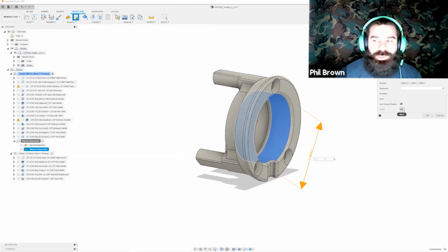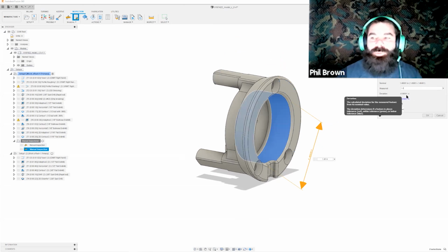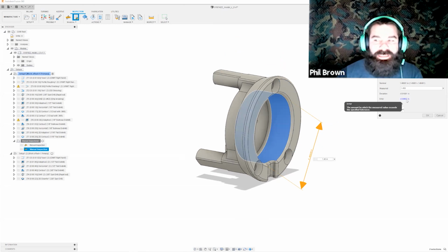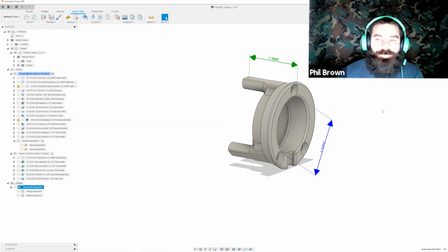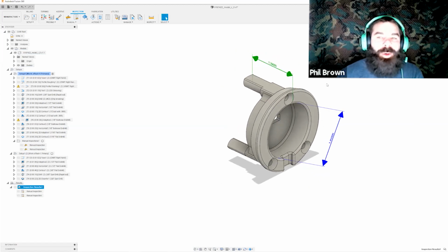So I don't have to look at the print, go back and forth a couple times, second guess myself. The same thing would happen if I say this comes out to 1.450, I now have an error deviation of 6 thou. So I'm actually out 10 total, but I'm still 6 thou out of tolerance. Well, hopefully when you guys go to do your parts, they come out good.